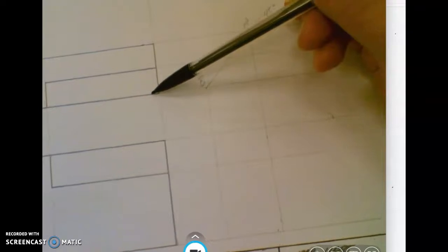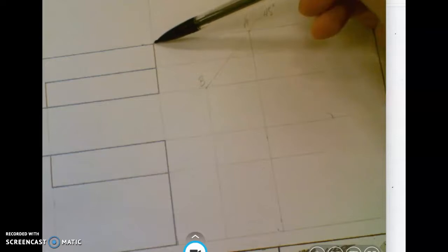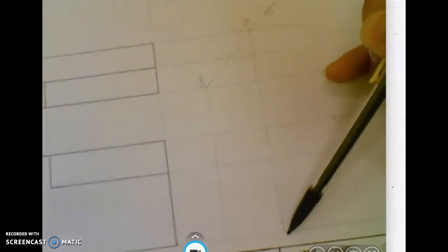So, as I mentioned before, we dropped the top. So we dropped this front edge of the top view to the miter and dropped it straight down. We took the back edge of the top view over to the right to the 45-degree miter line, dropped it straight down. And if you notice, I have one more construction line I have not dropped yet, and that shows this detail here. So this one comes to the 45-degree miter line. As you can see on your screen, it doesn't drop down. So that's what's missing. That's the last piece.